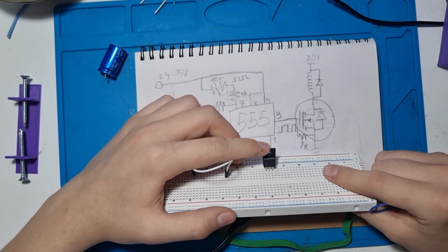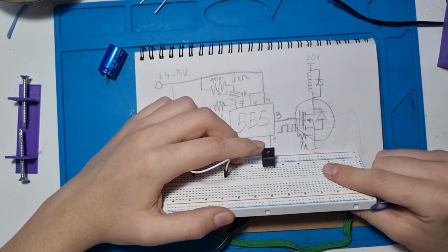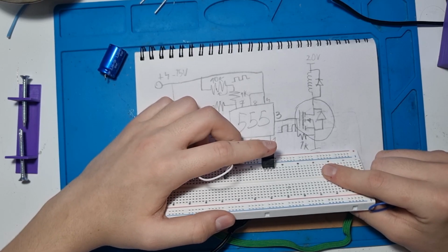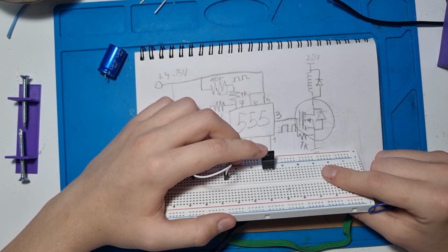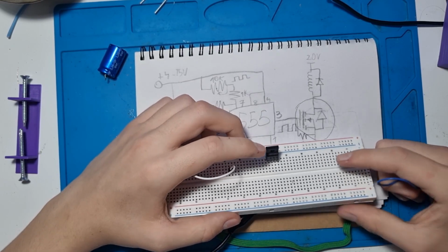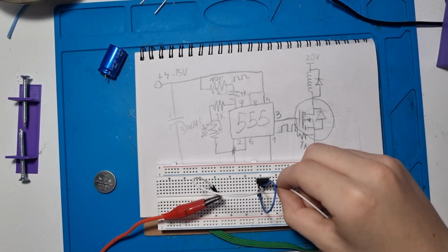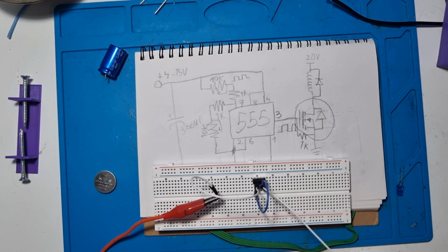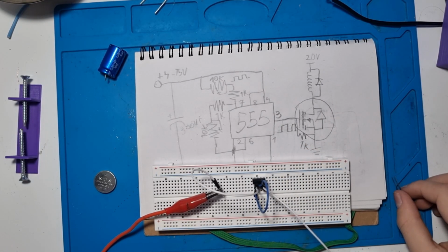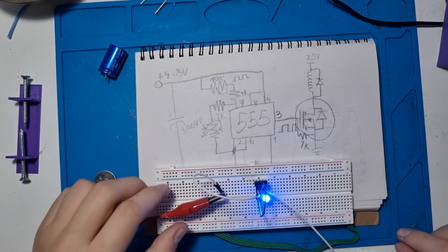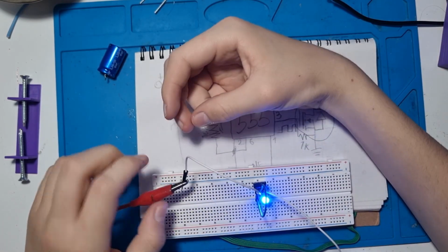Now, almost every MOSFET is gate, drain, source. You can learn it as good day sir. So if you can learn good day sir, you know, gate, drain, source. And then put the ground right here. Source is always ground, because if not, you will kill the inner diode of the MOSFET. And now I can use this as a switch. I can still power this on.